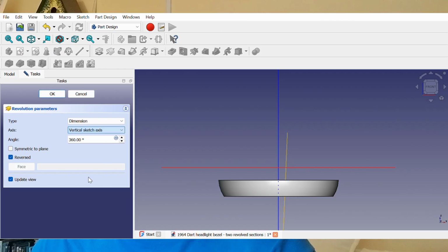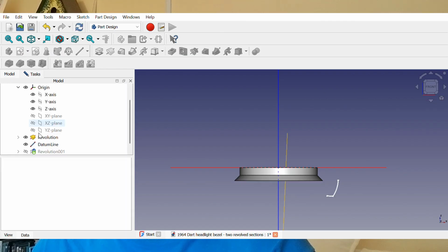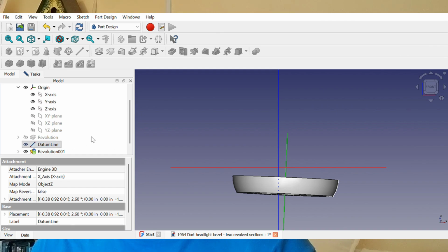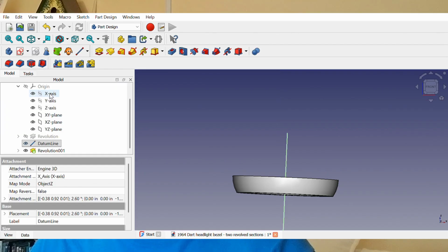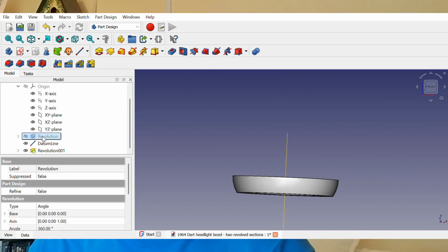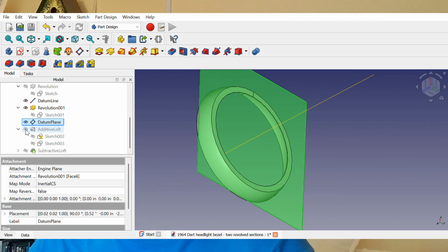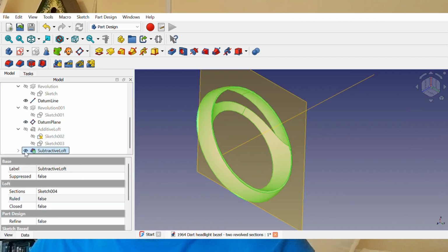But I ran into another FreeCAD limitation. It requires a part body to be one contiguous shape. You can't model a portion of the part here and a portion of the part there, then model what connects them like you can in a commercial CAD package. When you model a new section, the first one disappears. It's still sort of possible to grab the two portions and use an additive loft tool to connect the parts, but something breaks. It just doesn't connect the two sections together correctly.